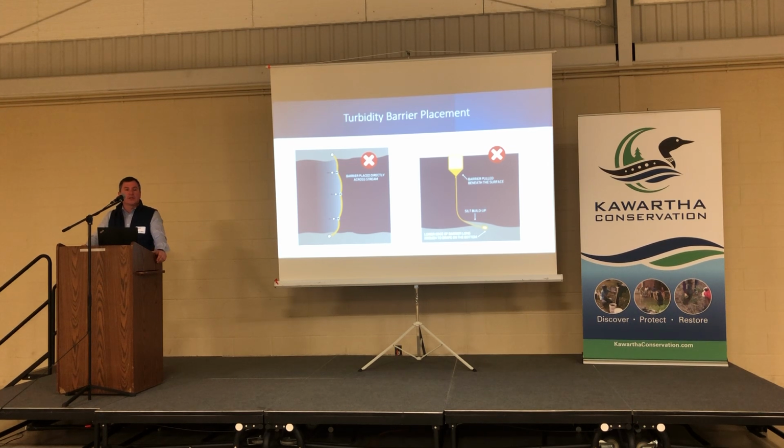Not effective. The curtain can many times be overpowered by the stream, and the sediment will just be pushed through and carried further on downstream. So they're not designed to be moved, to be installed across a water body.